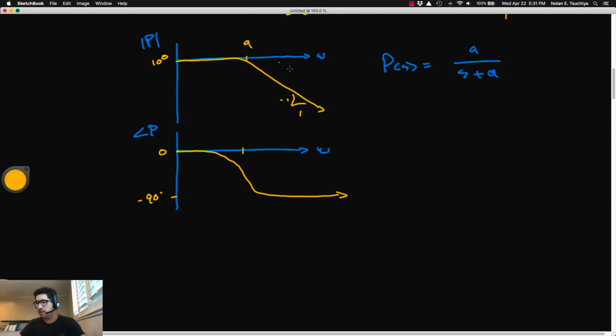Okay, and the main idea here is that this is a low-pass filter because it will allow, and we verified this for a few frequencies in a previous lecture, all these low frequency components to pass through with the same magnitude as the input, right? The magnitude for all of these is 1. So the output amplitude of the sine wave will be the same as the input amplitude. Moreover, the phase will be unaffected. So the output essentially equals the input for lower frequencies.